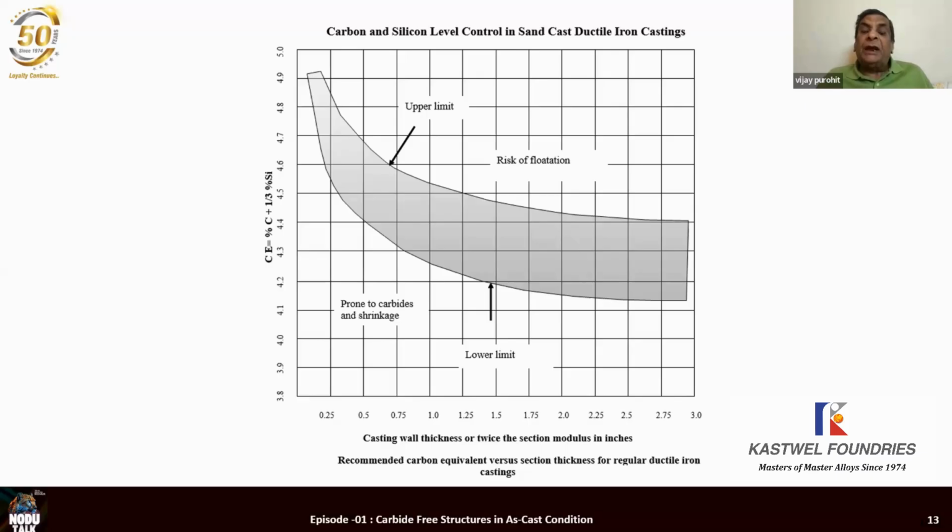Sometimes you may even have to go to 3 times. So when you make the pattern, make sure you measure the radius all over the pattern along with the casting, and then determine if next time you have to increase to 2.5 times or probably more than 2.5 times. So I hope this point is clear. The fillet radius in the SG iron patterns is very, very important because they are the one source of shrinkage because of heat concentration at the joint of the two surfaces.